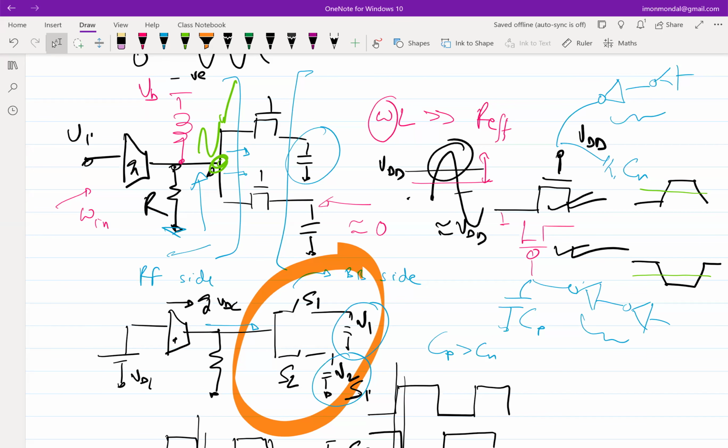But that's not true for a PMOS. You may have an NMOS with a threshold voltage of 400 and a PMOS which at some corner has a threshold voltage of minus 400. But if you slightly change something, this PMOS can become minus 450, while the NMOS remains at 400. So the turn-on times can vary a lot because they are completely different sets of processes, the way you make a PMOS or an NMOS.